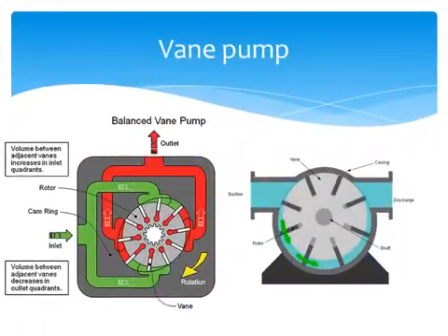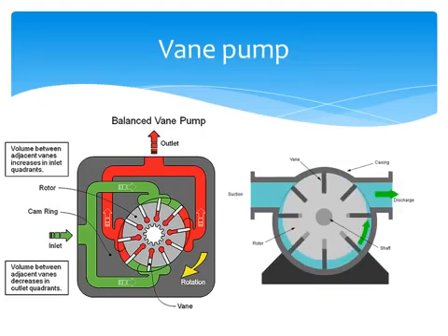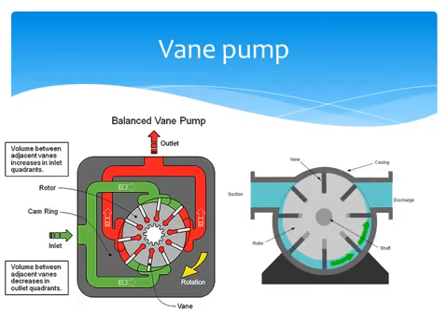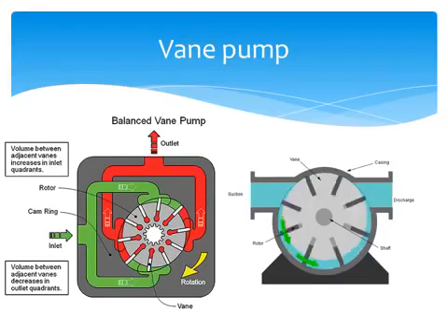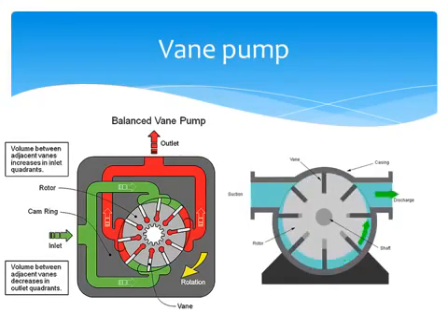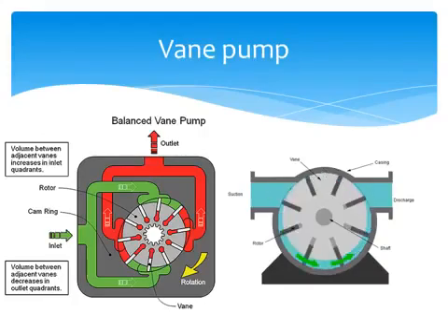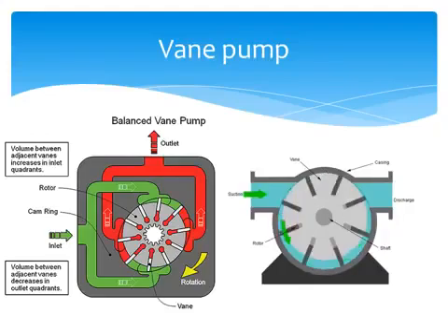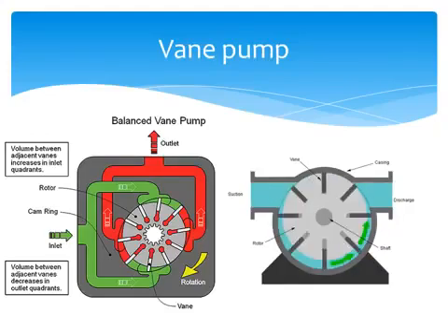The simplest vane pump is a circular rotor rotating inside of a larger circular cavity. The centers of these two circles are offset, causing eccentricity. Vanes are allowed to slide into and out of the rotor and seal on all edges, creating vane chambers that do the pumping work. On the intake side of the pump, the vane chambers are increasing in volume. These increasing volume vane chambers are filled with fluid forced in by the inlet pressure.